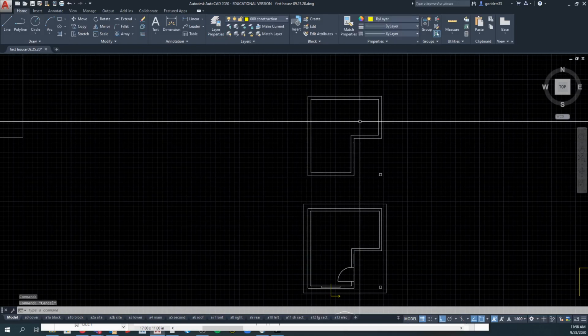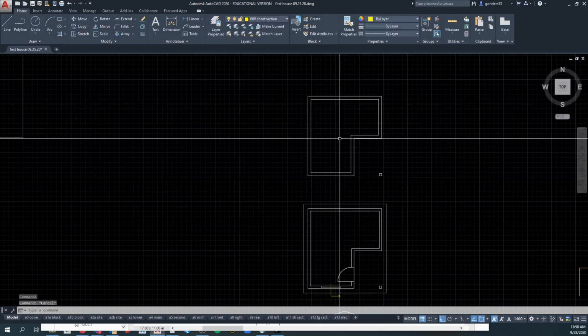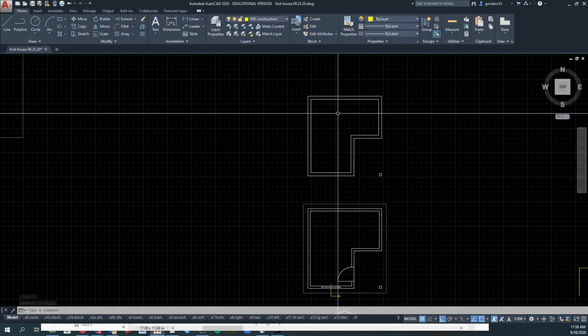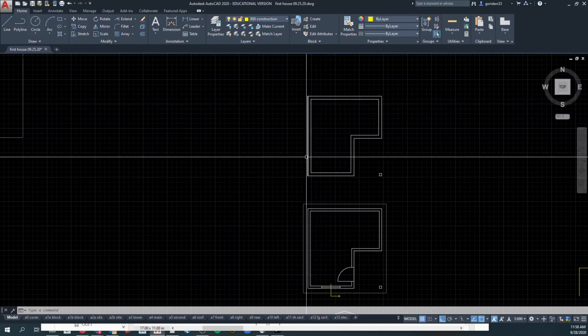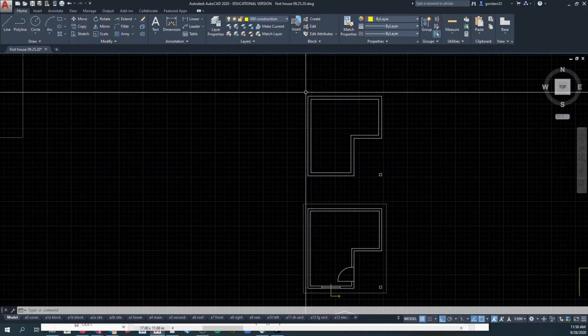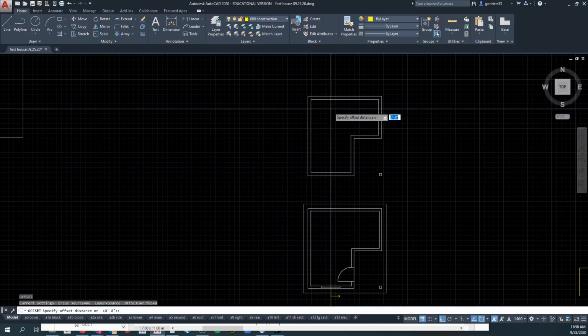So now I want to make a footing. This foundation wall is an 8-inch thick concrete foundation wall. It's got a 24-inch footing underneath it, and the footing sits directly over the center of that. So if I have a 24-inch footing and an 8-inch wall sits directly over top, that means the footing sticks out 8 inches to the outside and 8 inches to the inside.